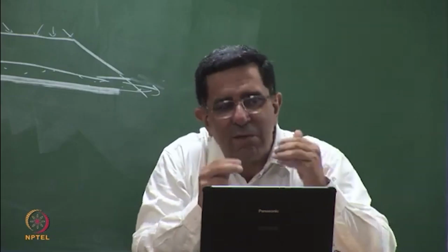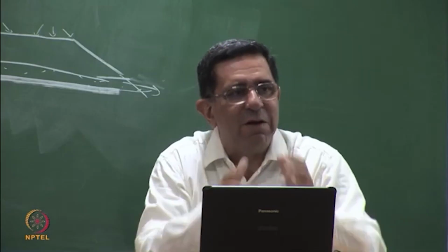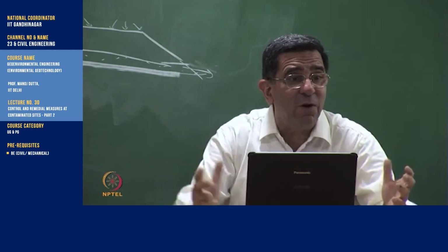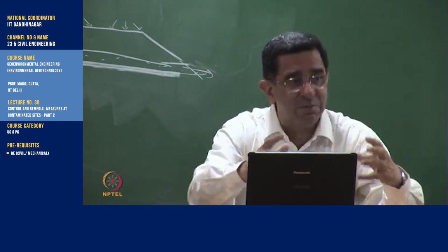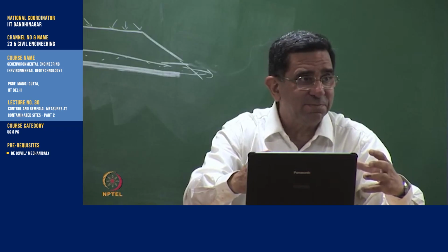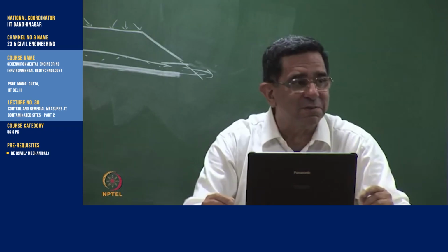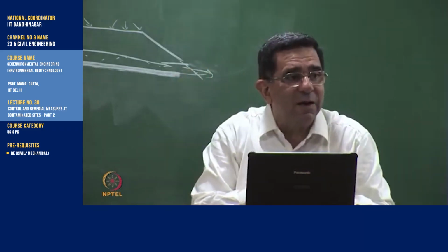You use some PM9 or some other grout, chemical grouts, they also have limitations in penetration. And in any case, you are not able to give a uniformly cemented matrix. Where your hole will be, maximum cement will be around the pipe, maximum cementitious material. As you travel further away, the cementitious material will be less. How do you assure me that it's equal everywhere?